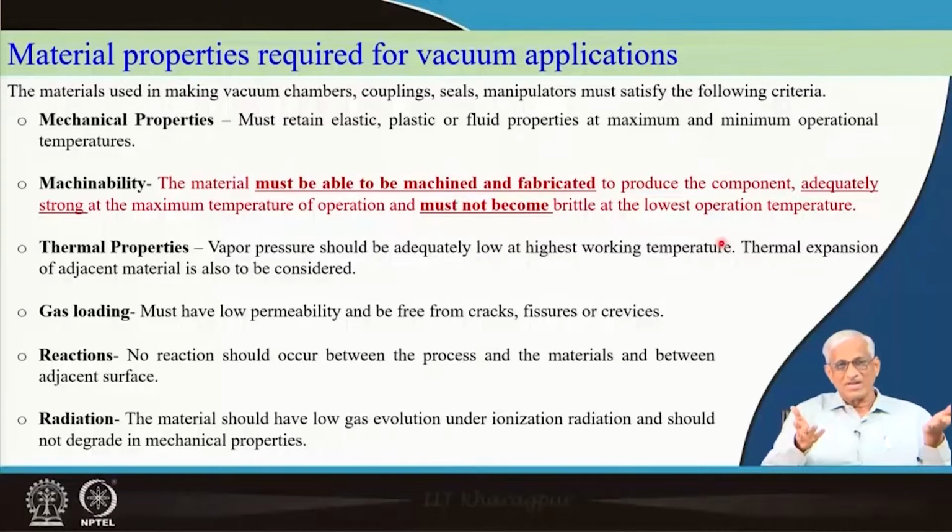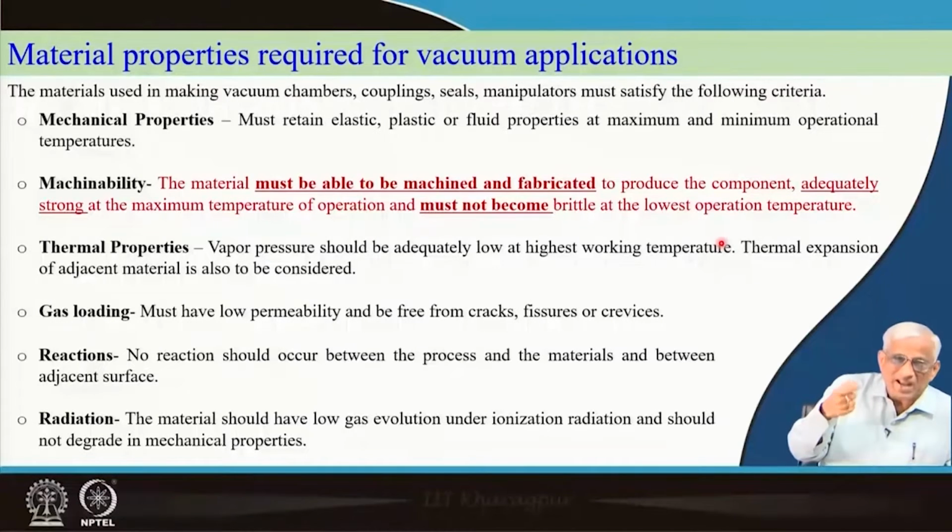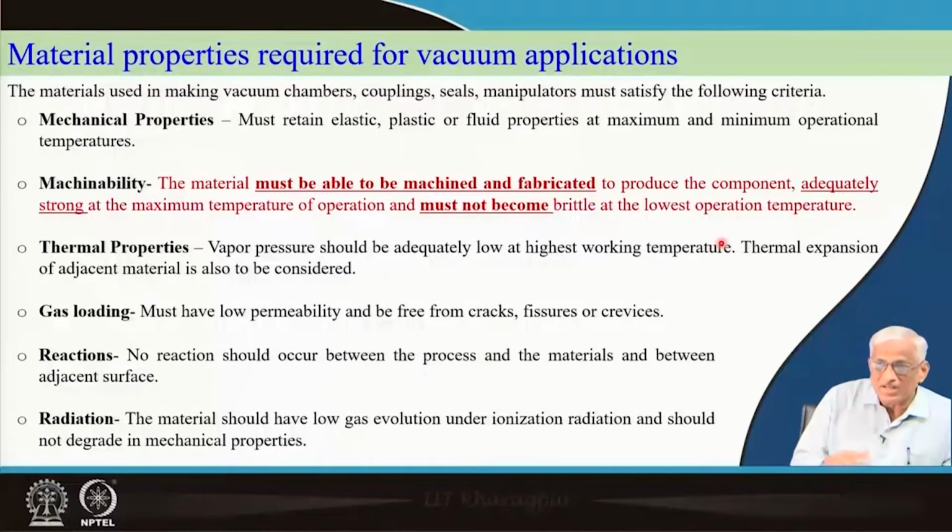It should be strong. After all, under vacuum, because of elastic instability, the chamber will collapse if you do not have a strong material, or if you have chosen a wrong thickness, or if there are some flaws, some cracks in that material, because it is a low cost material. Same stainless steel, very high grade quality can be very costly. There may be a cheap material, sometimes it may be okay. So, you should be judicious in choosing the material.